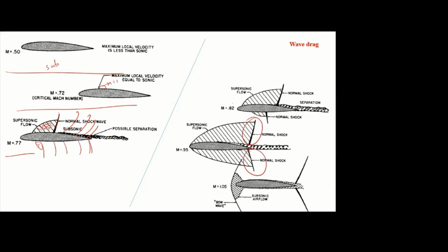Okay. And if you further increase, up to this, it is subsonic only. See, Mach number is less than 1. And once it is supersonic, there will be an additional wave in the front. That is called bow shock. So bow shock is the combination of waves. In the center, it is like the normal shock. And this inclined shock is called oblique shock. And this is called Mach wave.